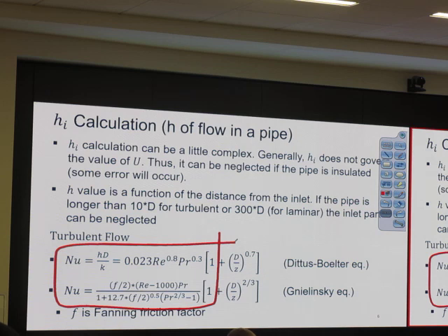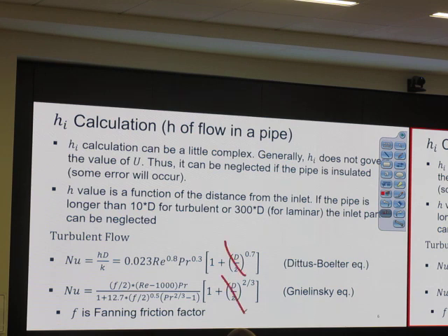So in the exam, when I give you this formula and I say fully developed heat transfer, you may assume and neglect those terms. But I don't think the exam is going to be that difficult. So the Nusselt number changes with position if we are far away from the inlet. For example, 35 diameters away from the inlet, we should be safe using just this term.